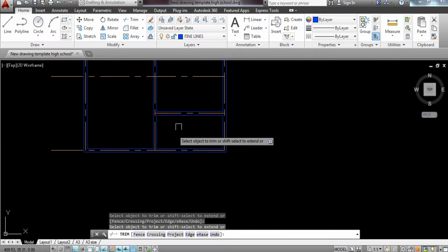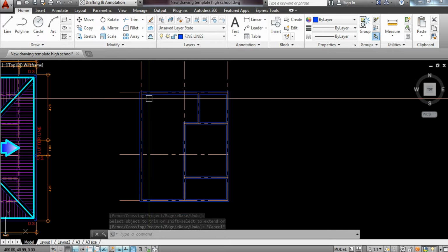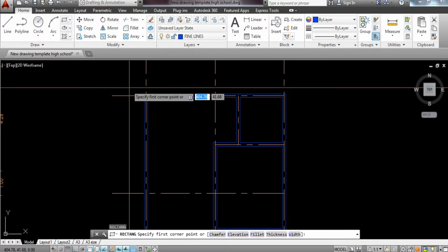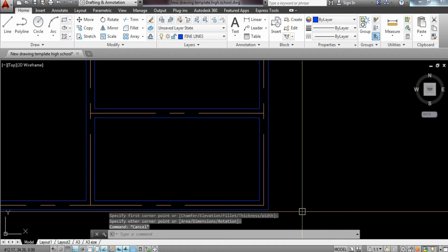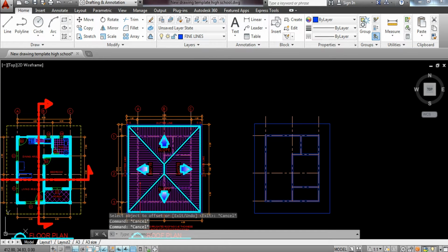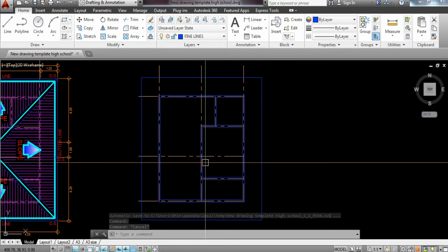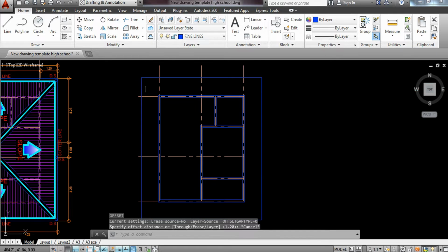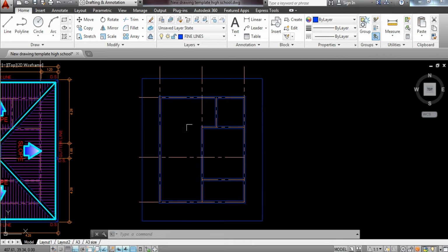Okay, so there you have it already, the position of the placement of the walls. Now I'm going to also add here REC for the position of what we call the roofing. So offset ako ng 1.2 going outside. So this represents the roofing that we are going to have in our structure. Now, if you want to automatically indicate the gutter line, hindi naman na siya kailangan kasi ilalagyan pa natin siya ng soffit dito. Okay, make sure na sa under 0.20 siya. Pero iisa-isahin muna natin.